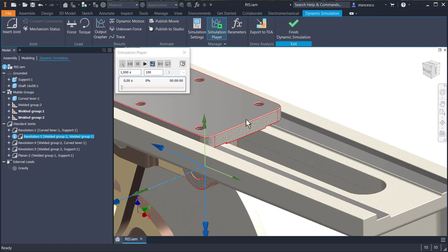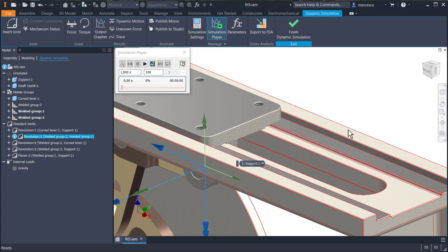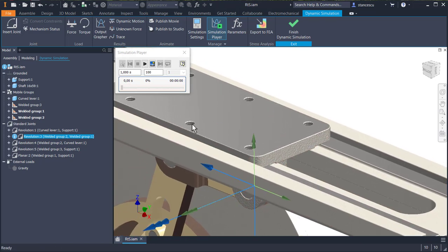When we placed this object on this face with mate, we constrained 3 degrees of freedom, 2 rotation and 1 translation. Translation on Z, this Z, and rotation about this axis, and rotation about an axis parallel with this.